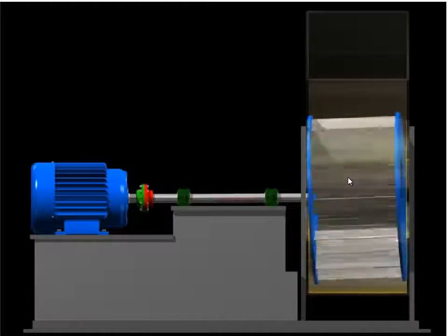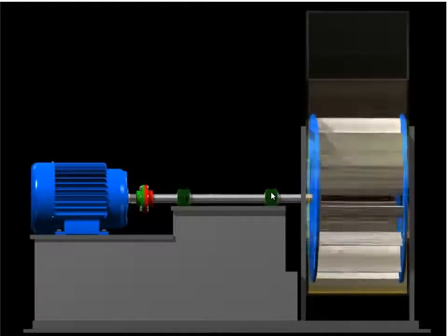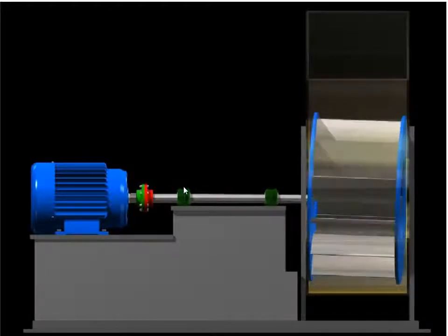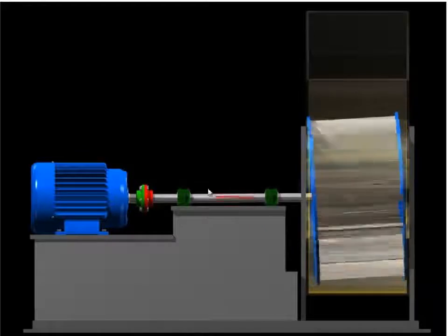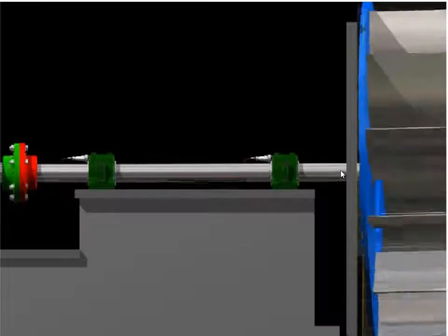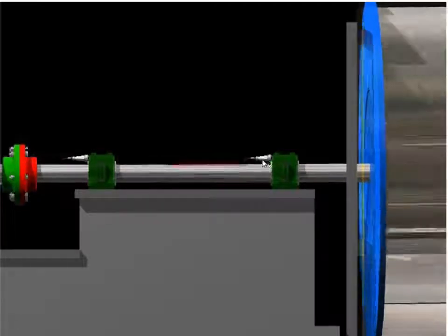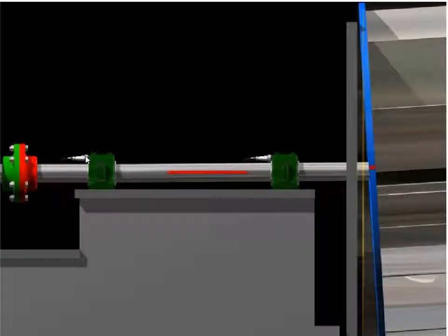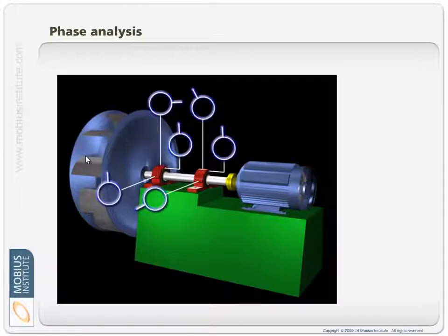So it's still circular motion, so our 90-degree rule applies here and here, but we create axial vibration as well. So we measure that and we look at the phase reading. So we put our sensor axially and see what happens. Now this all might seem just a little bit complicated.